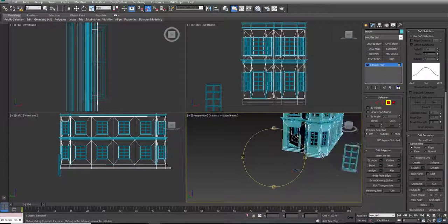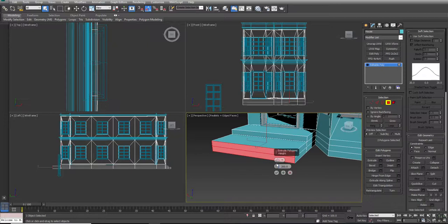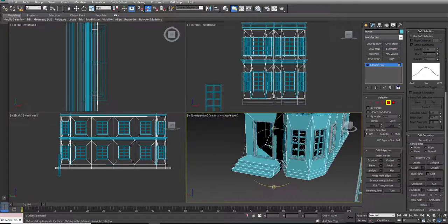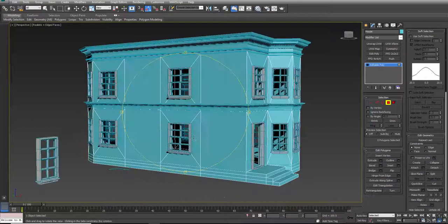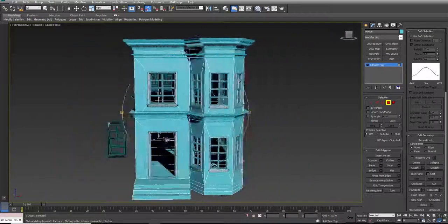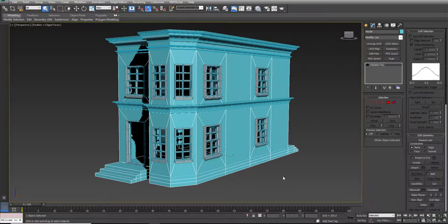And we can go around the back side and do the same thing. Zoom in here. Select 1, 2, 3. We'll extrude those out 200. Deselect the top one, and then we'll just extrude these out 65. Deselect the top one. Oops. Select only the bottom and then hit semicolon to repeat. Alright. So there we have our basic house. It's looking pretty good. In the next tutorial, we're going to talk about how we're going to go through and UV unwrap this house.